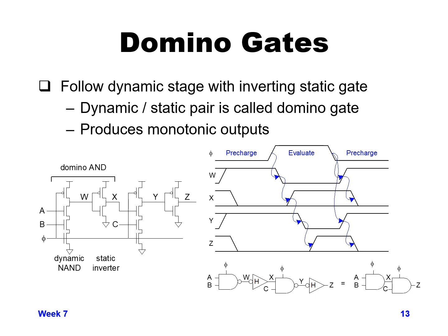but because it's an inverting static gate, we can follow it by another domino stage after, as long as we have an inverting stage in between, because the domino stage will start high. That means any inverting stage in between will have its output low, because if all of its inputs are high, and as long as that static stage only has domino stages driving it, all of its inputs will be high, so its output will be low, and then a following domino stage will be taking the output of the static stage, which is guaranteed to be low during precharge.